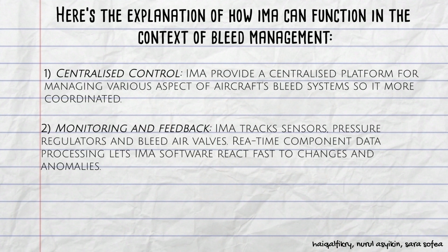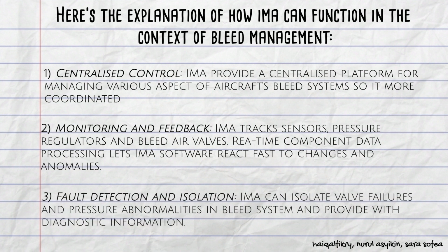Additionally, IMA excels in monitoring and feedback. IMA modules actively monitor the status and performance of the bleed air system components, including valves, sensors, and pressure regulators. Real-time data feedback from these components is processed by IMA software, enabling the system to swiftly respond to changes or anomalies.